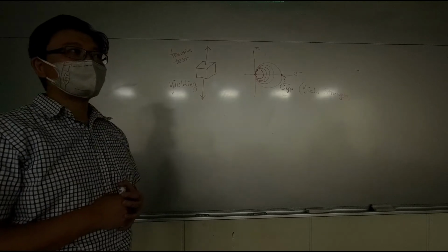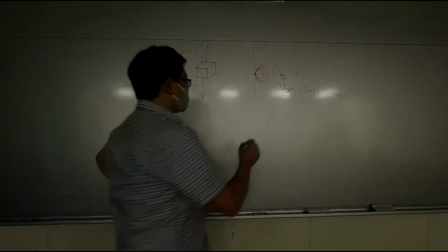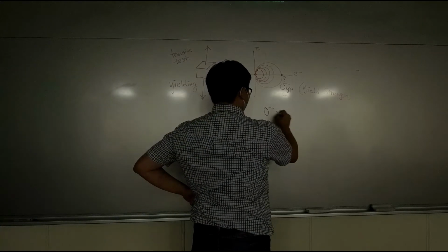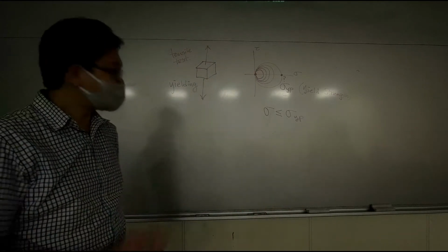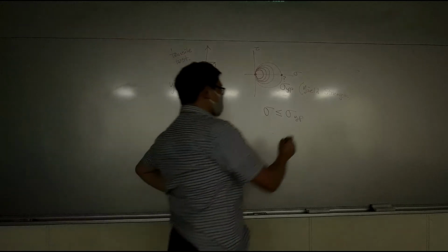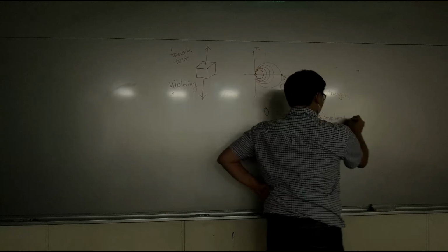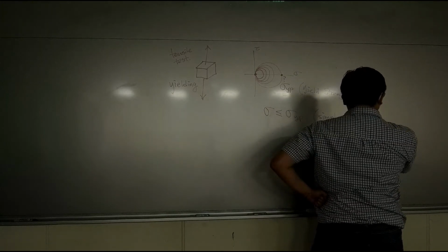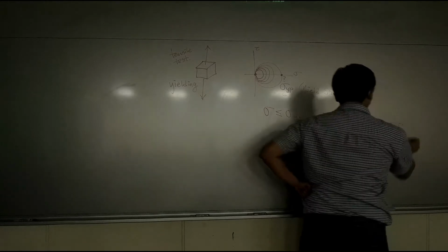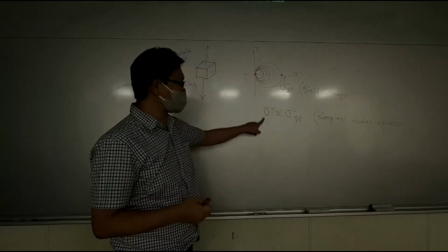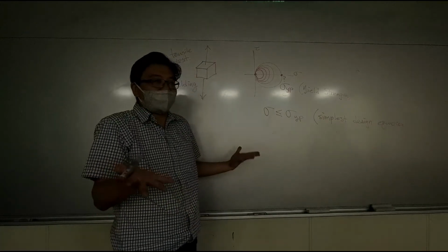So it seems like if we can design a material where our stress is less than the yielding point, we are in good shape. So that's the easiest concept, the simplest design equation. We just make sure our stress is less than yielding strength, then we're okay.